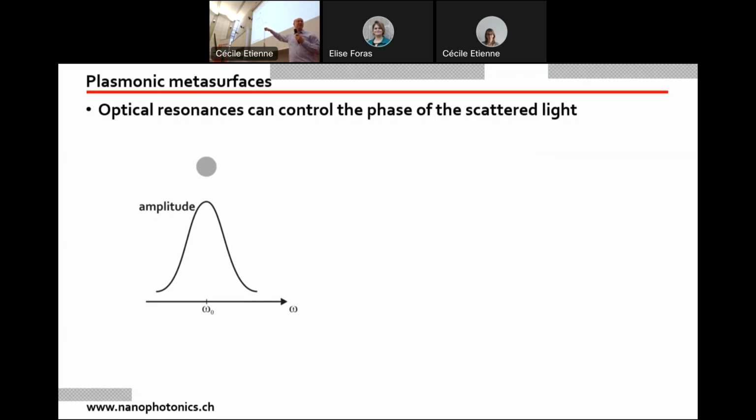But now if I change the frequency, and if I go across the resonance frequency of the system, you don't see it very well because the spring is a bit stiff, but what happens is that beyond the resonance frequency of the system, my hand goes down and the mass goes up, and my hand goes up and the mass goes down.